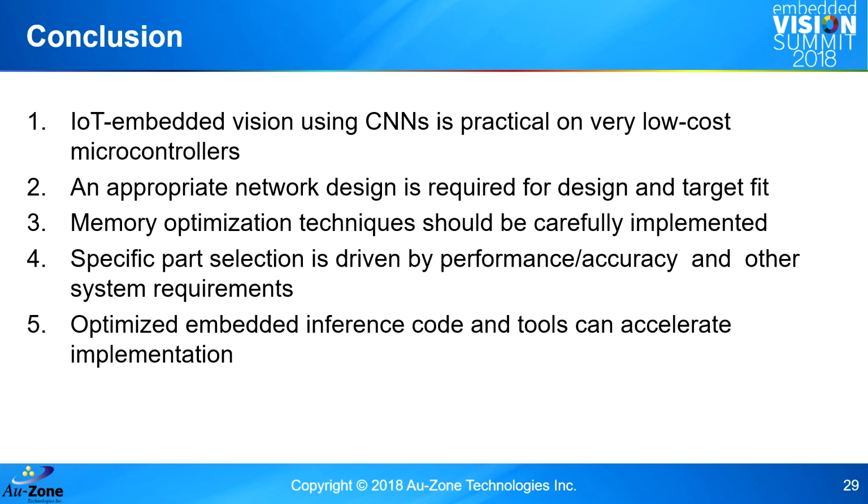So if you needed a larger network for this particular application or higher accuracy, you might have bumped up from the M4 to the M7 microcontroller to gain that extra performance. And you can leverage development tools, such as the one I've shown here, to help the design process and reduce the risk of implementing these kinds of designs across a wide selection of hardware.